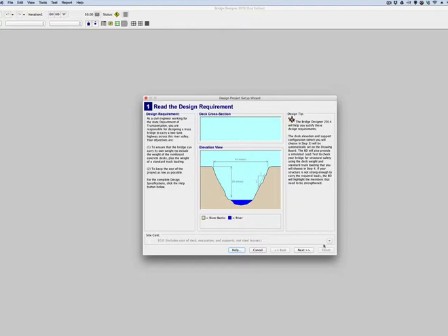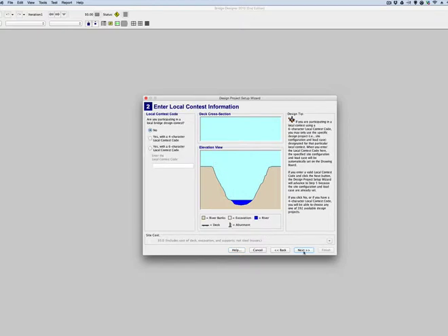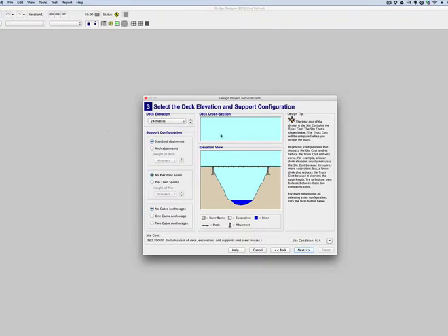In the beginning, when the first time I do something, I tend to go slow. No, so you don't need to worry about that code. Here is the deck elevation right up here. Standard abutments. I don't have arch abutments. I have no pier. If I put a pier, it starts showing up here. And you can put it in there. But notice what my site cost does with that. If I get rid of it, it's a question of almost $40,000 there.